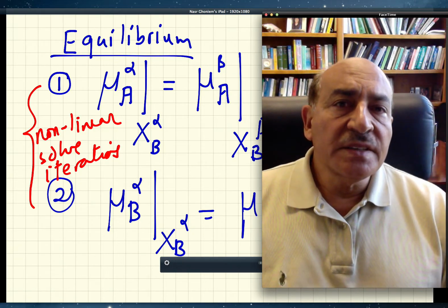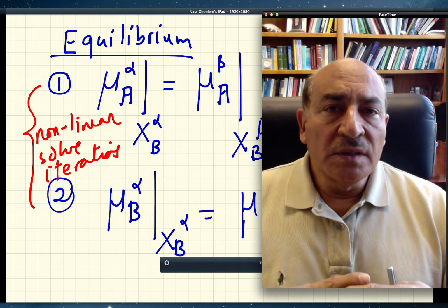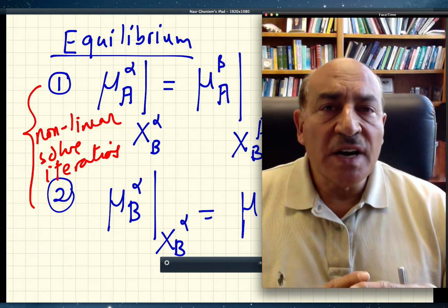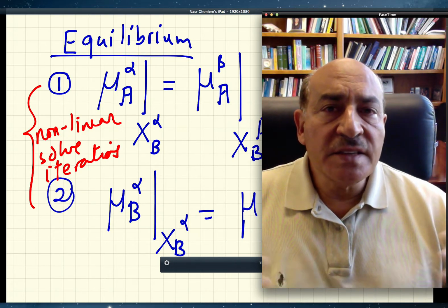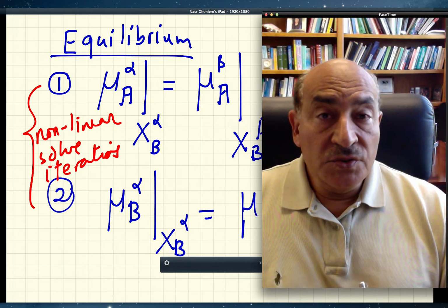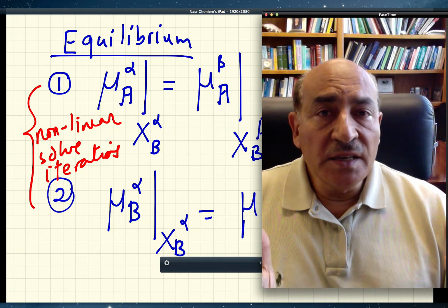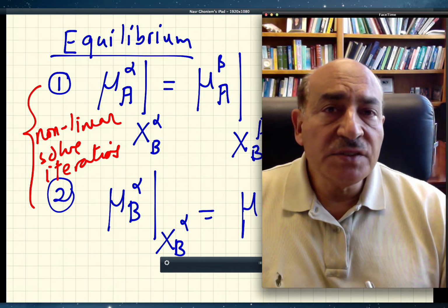This is the procedure that we have for two species. Graphically, we would just use the common slope for the free energy in the alpha and the beta phase, and the intercepts on the left and right will give me the solution, and the concentrations will be those determined to be at the common tangent.